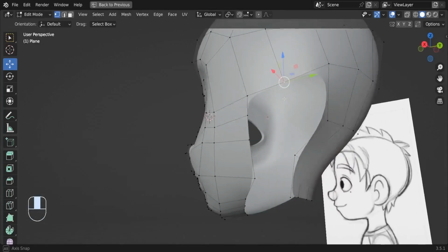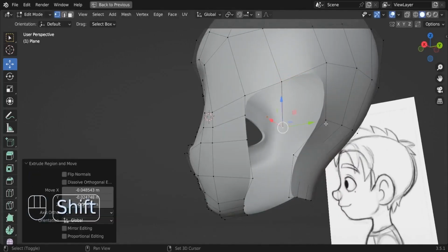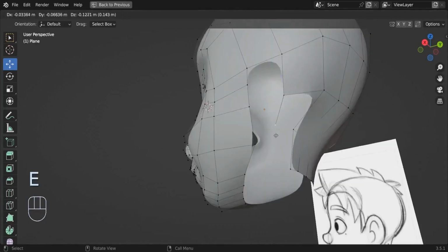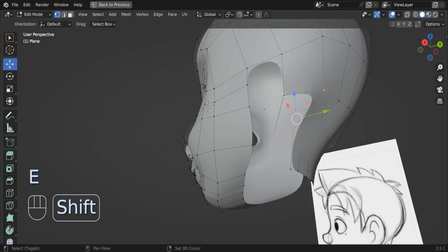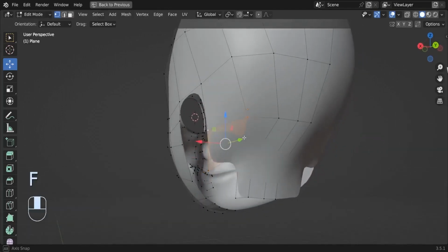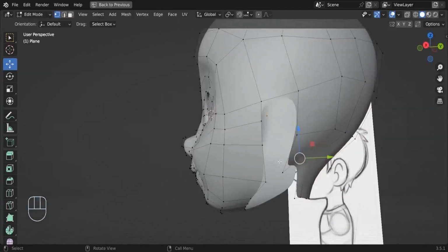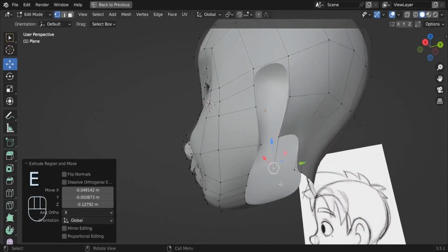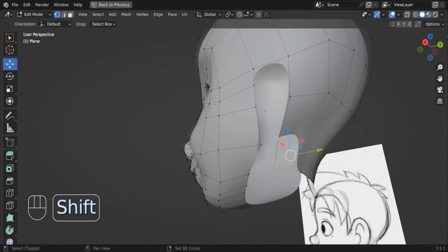Okay, so here we can extrude down, extrude this vertex, and we can select these 4 vertices, press F to fill them, and let's do the same thing again. You can extrude again, select these 4 vertices, press F. Let's try to push this vertex outside, select the last vertex, extrude it down. You can select these 4 vertices.